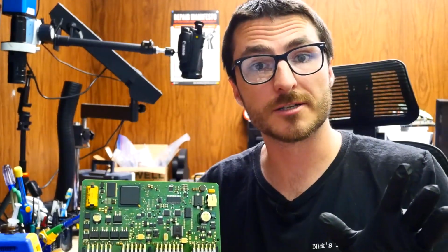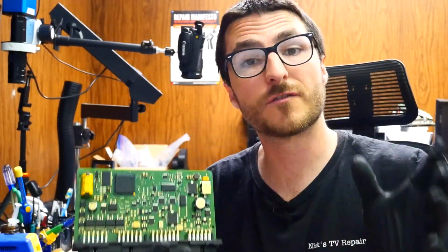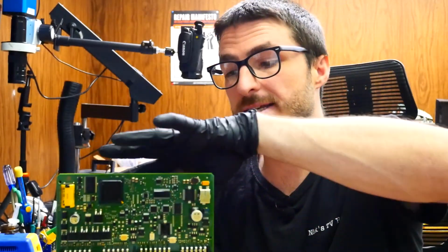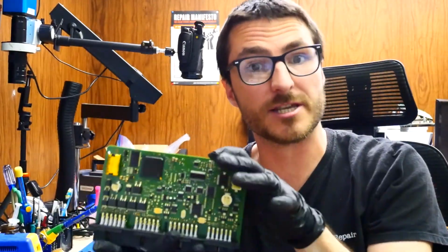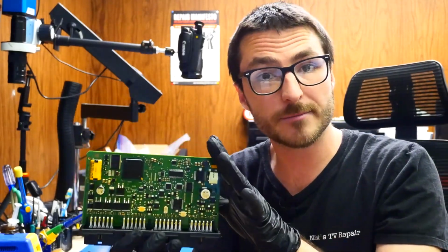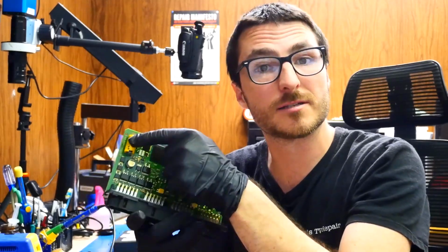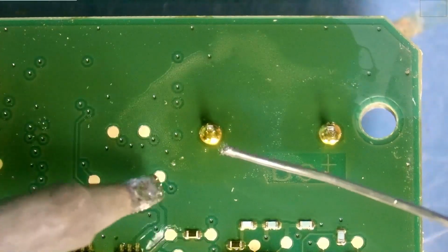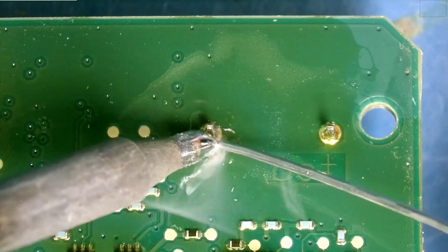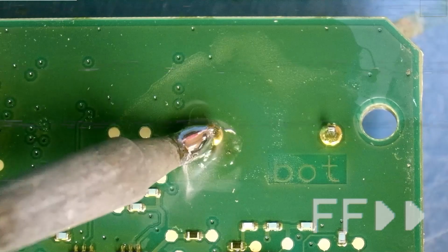Now, in order for us to be able to replace all of that solder between the processor and the circuit board, we first need to remove the conformal coating. That conformal coating is that glossy surface that is essentially weatherproofing this circuit board. In order to do this, I'm going to have to dunk this circuit board into some chemicals, but in order to do that safely, I'm going to have to remove this lithium-ion battery that is soldered onto the board. So to remove the battery, we're going to desolder 3 joints. And again, this is completely coated in conformal coating, so I have to burn through it a little bit first.